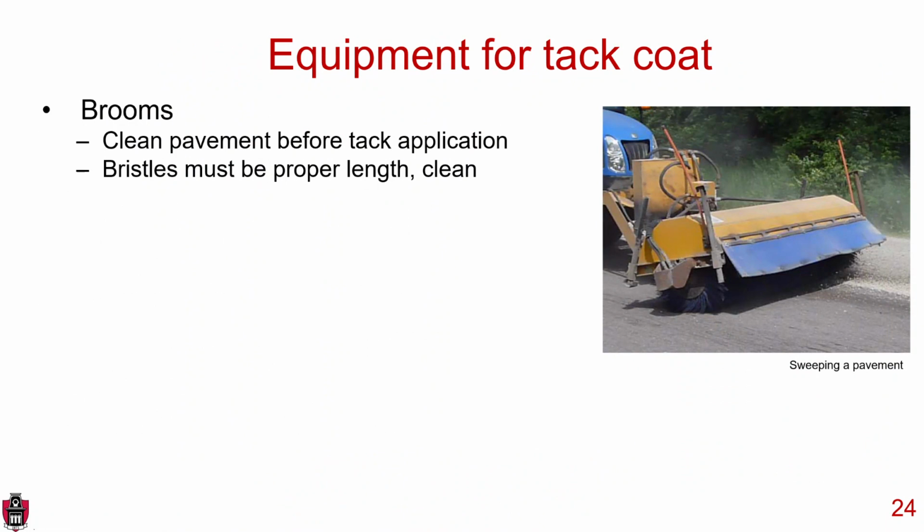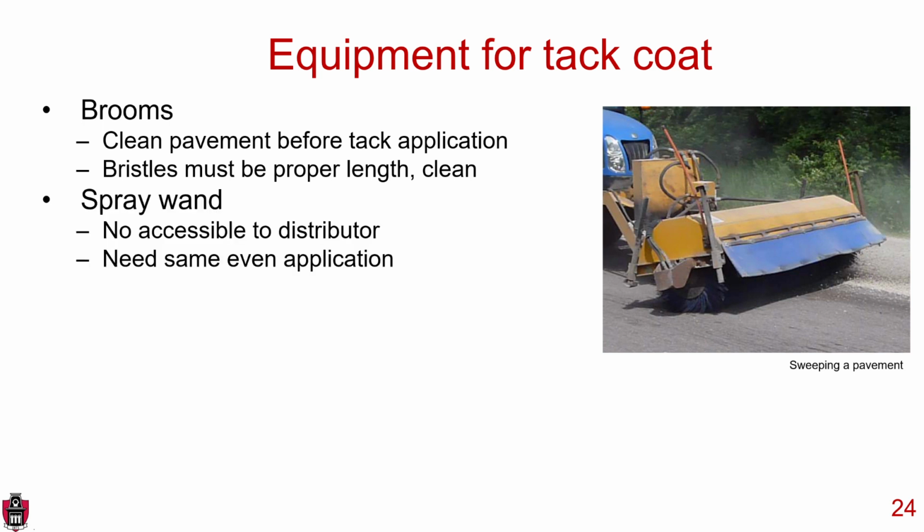Now, what sort of equipment do you need? You need brooms. You want to clean the pavement before your tack applications. There's really very little guidance about how to keep your brooms in good shape. There is some discussion about bristles being a proper length and the bristles being clean, but you need a clean surface and you need a broom to achieve that.